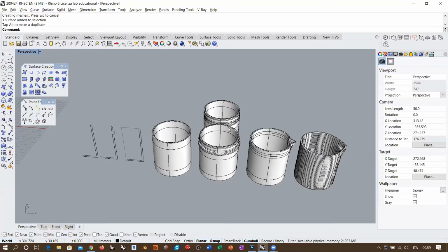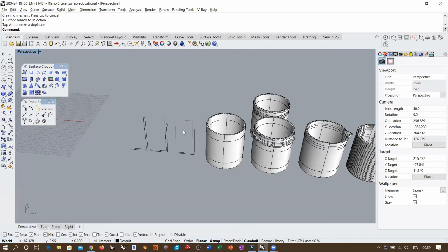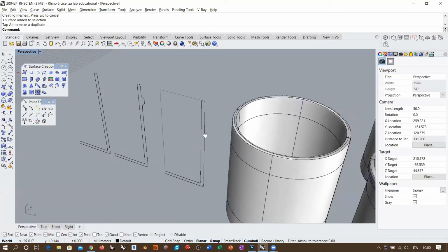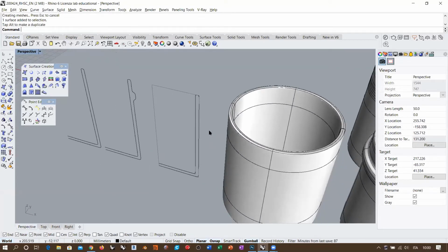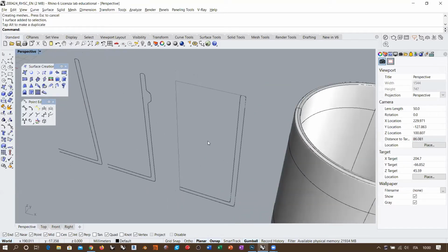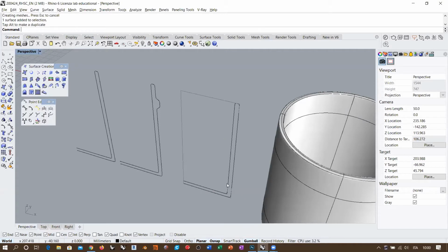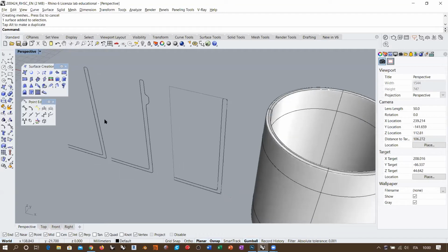Then there is another type of revolved surface, which is somehow problematic, but it can be useful to create some nice, let's say, complex revolved surface also from the rotation point of view. So you might know, for example, that there is a right-click command which is rail revolve, where you are allowed to select not necessarily a circular revolve, but a revolve which is determined by a rail curve. So you will have profile curve, axis curve, and rail curve.